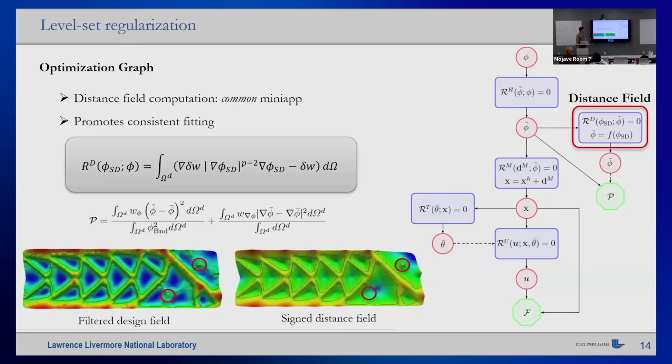The second thing we use is a level set regularization. In level set topology optimization, as I hinted, it sometimes happens, and it's only one example, that we have these disconnected islands. The design sensitivities are non-zero only at the boundary, so the island will probably disappear, but the moment the level set field sinks through the isocontour level, there are no sensitivities anymore, so it will just linger around. And now, when we use MMA, there are tons of different reasons, from round-off errors.